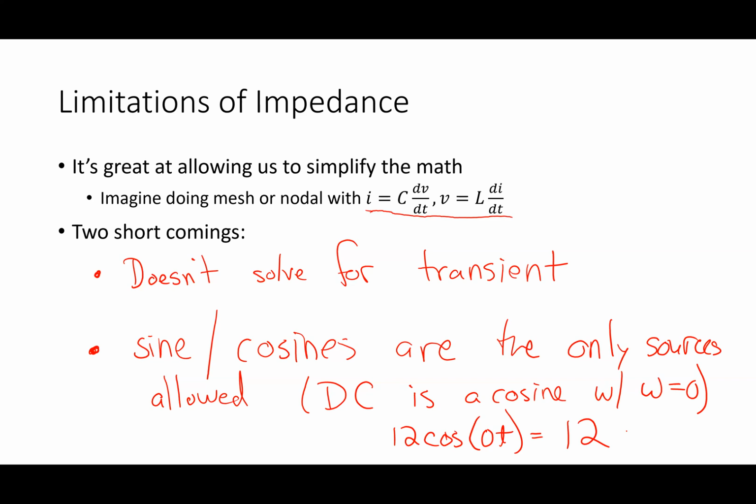For instance, in digital circuits, what's a typical input? A square wave. You get clocks, pulses. You get a clock that's a gigahertz or something like that. A clock is a square wave that basically just goes from low to high, low to high, low to high. If it's a gigahertz, it does that a billion times a second. That's not a sine wave. So there are all kinds of other inputs that exist in the world.